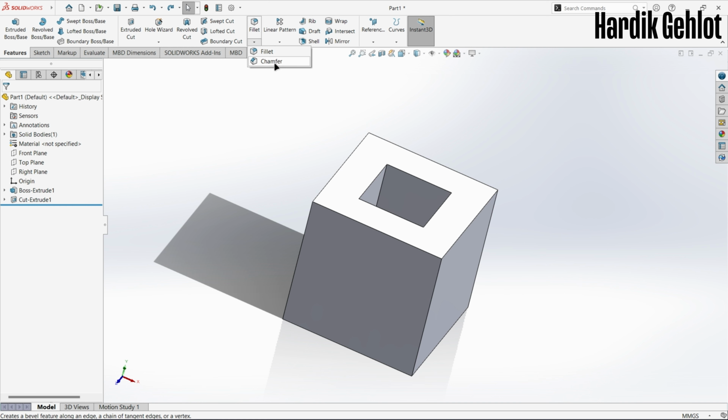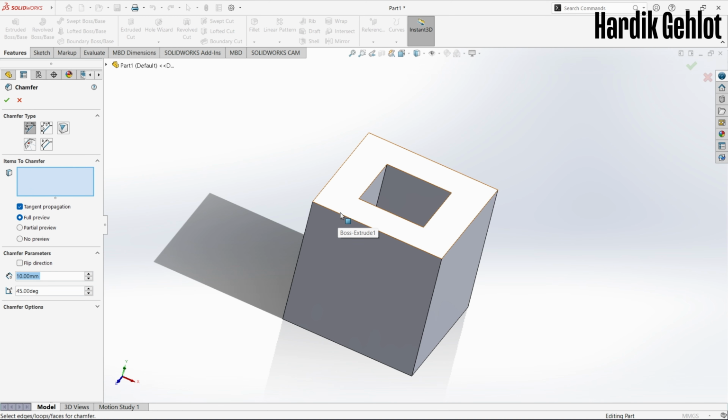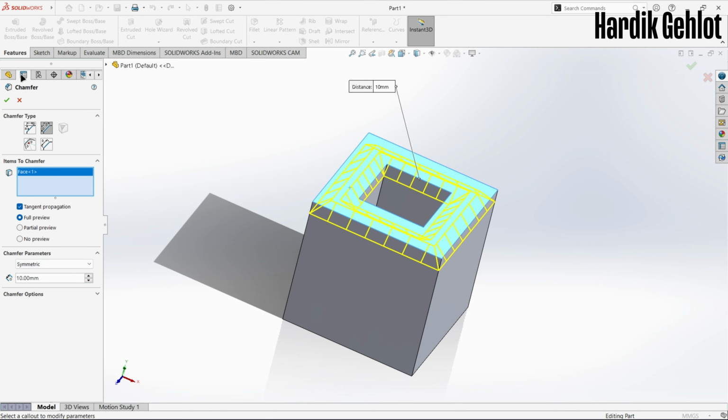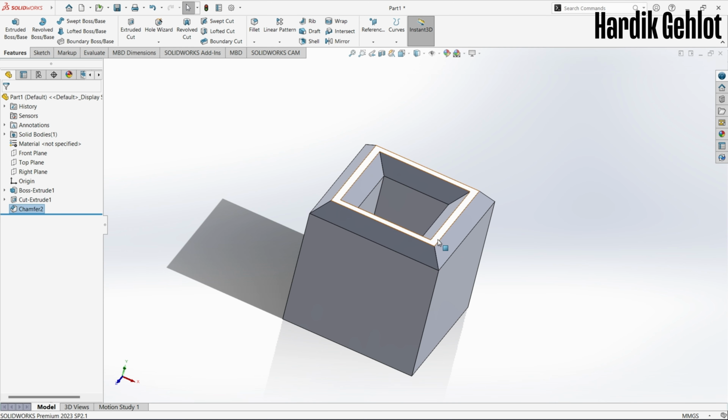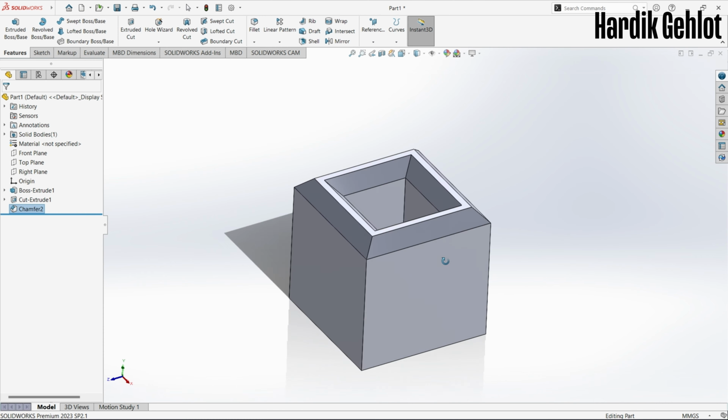Below the fillet, you will see the chamfer feature, which converts the edges into slopes. Select the edge and type: angle distance, distance, vertex, offset face or face. Similarly, you can select all the edges by selecting the plane. Mostly, angle distance and distance chamfer are used.